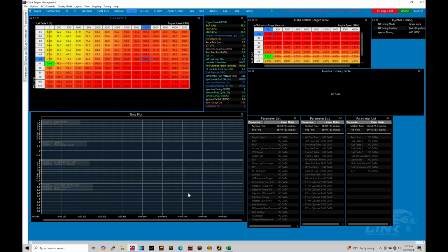When we're talking about a paddle shift option, we're controlling a sequential gearbox with a shift actuator to shift up or down when we're requesting the shift to happen off of our paddles, but it's also going to be working with air pressure, airline pressure. It has to have a certain amount of pressure to get the shift actuator to move, and we're controlling an air compressor pump to generate the line pressure and keep that consistent for the shifting.